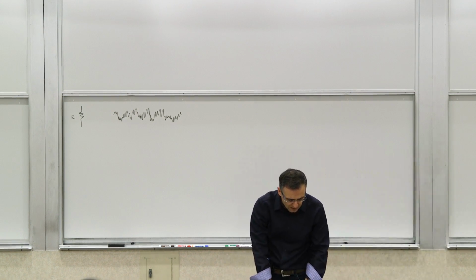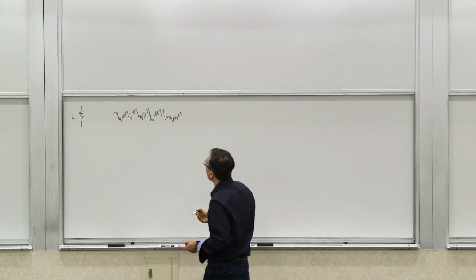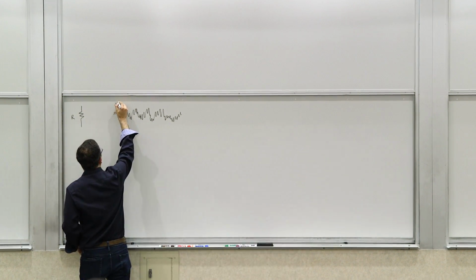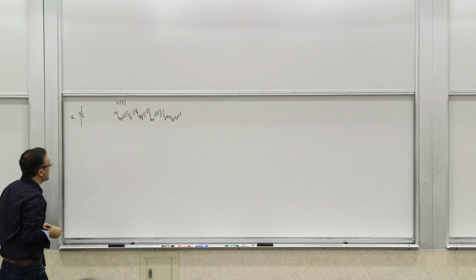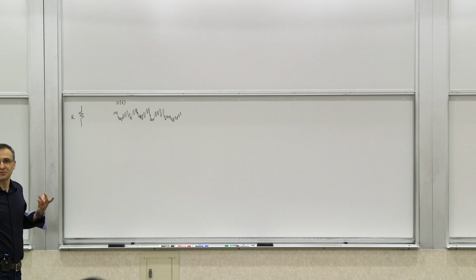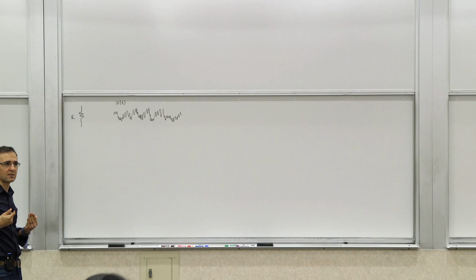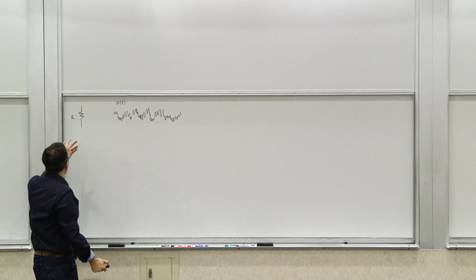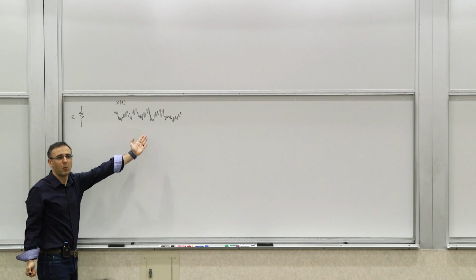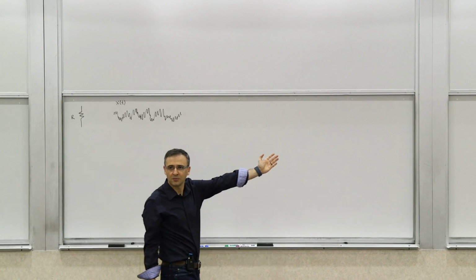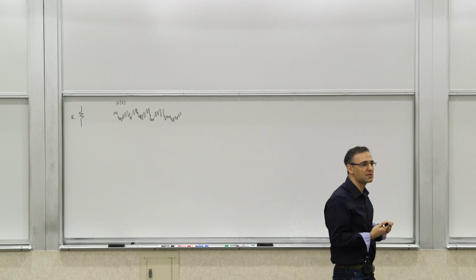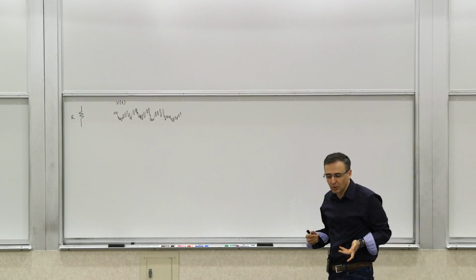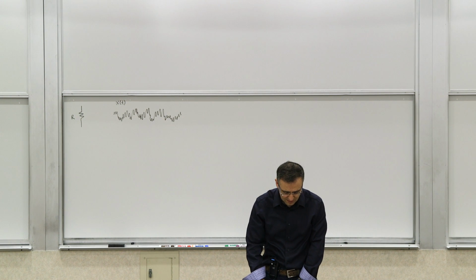But if you have a random process, and you look at a sample of the random process, let's call it x of t, there's no predictability because it's random by itself. So what you can only talk about is the statistical properties of these things. You cannot talk about this deterministically, because next time you look at this resistor, you will not see the same waveform. You see a completely different waveform. But the statistical properties of these things can be determined, and that's what we will be mostly concerned with.